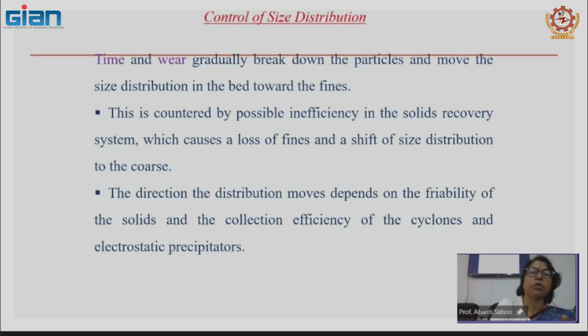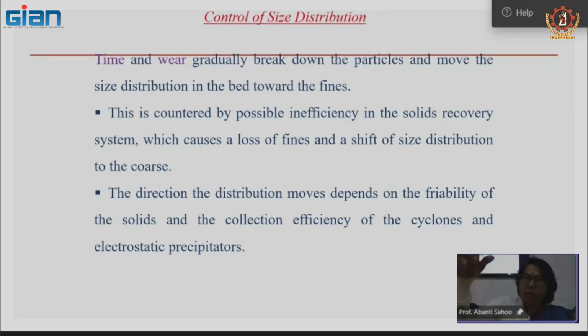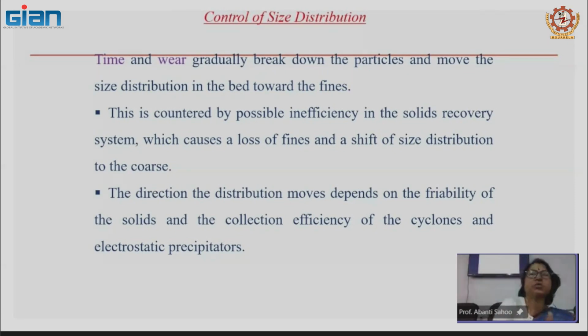If different sizes are there, then lighter particles will move to the freeboard region, and once they reach the freeboard region there is a chance of entrainment, because with the increase of velocity these lighter particles may leave the bed. That is entrainment. As a result, the amount of particles in the bed reduces and the size also reduces. That affects the size distribution, or if they are not carried over, they remain, and more and more fines will be created in the bed.